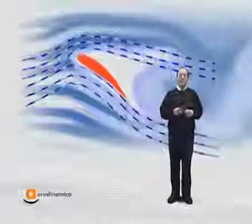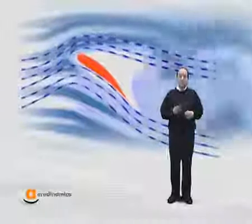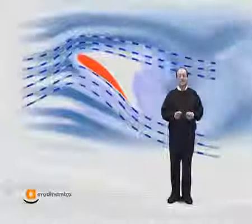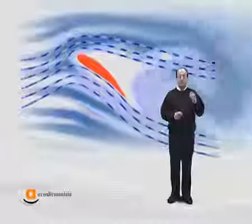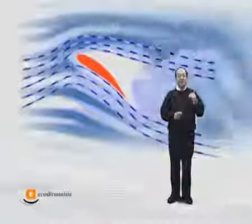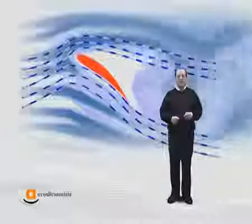What happens on the airfoil? Behind the airfoil, a wide vortex region is present, which disrupts the main flow, as we have already seen in the last lesson on drag. It makes the fluid separate from the body. In this condition, the so-called stall occurs. The flow separates from the body, having to flow around the vortex region.